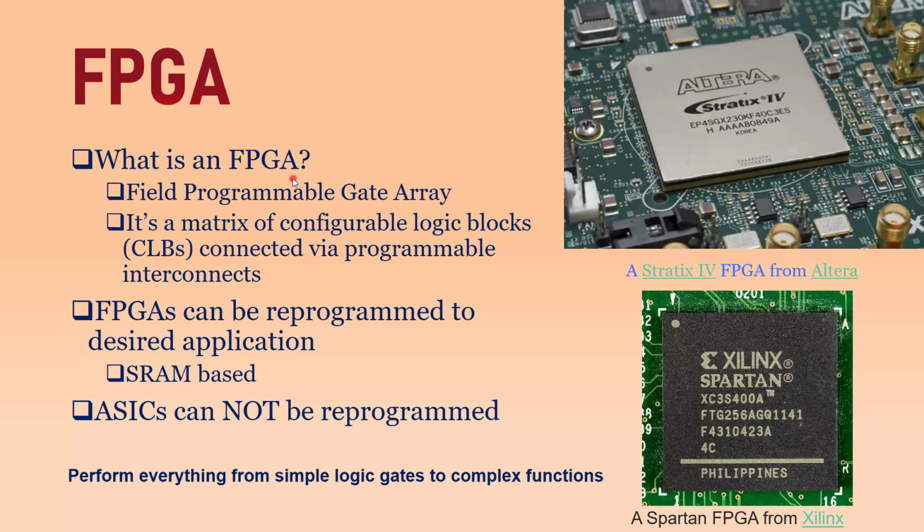So what is an FPGA? As I said, the word FPGA stands for Field Programmable Gate Array. As the name suggests, this is an IC which you can program again and again to realize any digital logic. From simple logic gates to complex functions, you can realize any logic in it. So this is a configurable, reconfigurable IC, and there are millions and millions of logic gates inside which you can program, and you can interconnect those gates to each other to realize a Boolean expression or logic function from simple to complex.